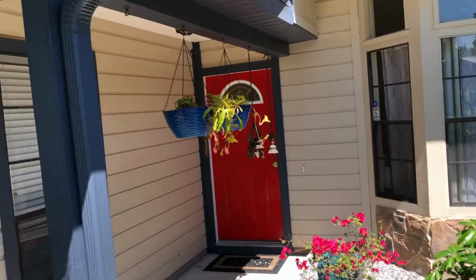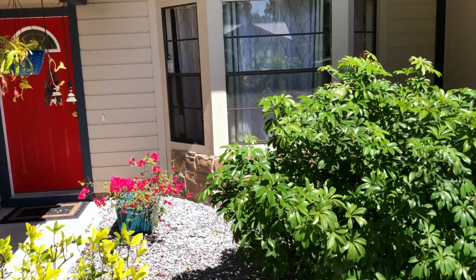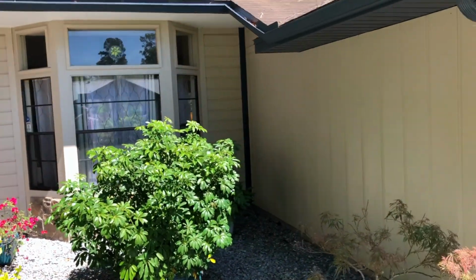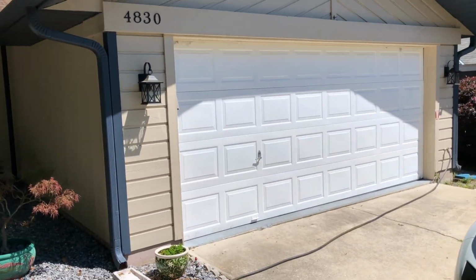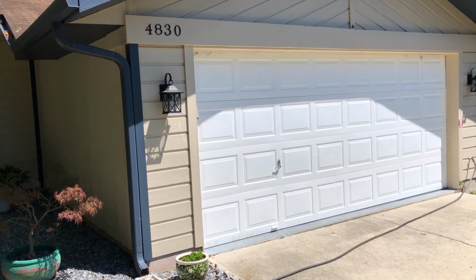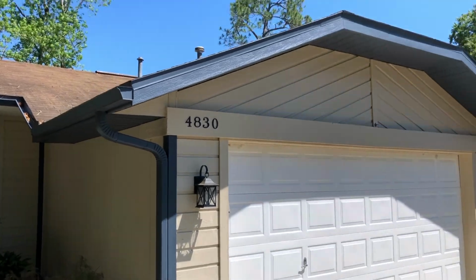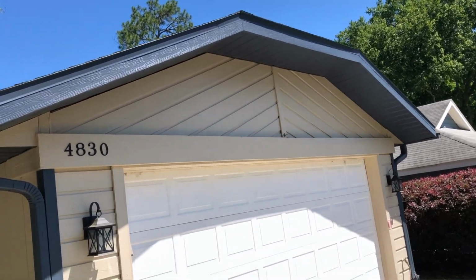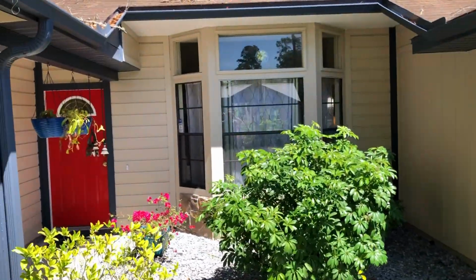And then I have eaves trying to protect where you walk in to keep it shaded. But this is classic over here. The eaves are designed so that in the wintertime, the sun would be low and it would all be getting direct sunshine. But in the summertime, when the sun is high, the eaves up there provide deeper shadowing and it keeps it in shade.